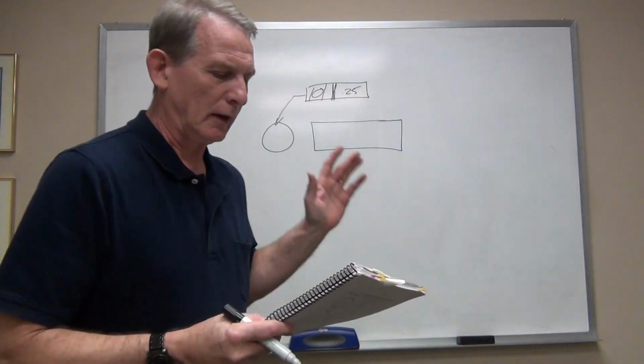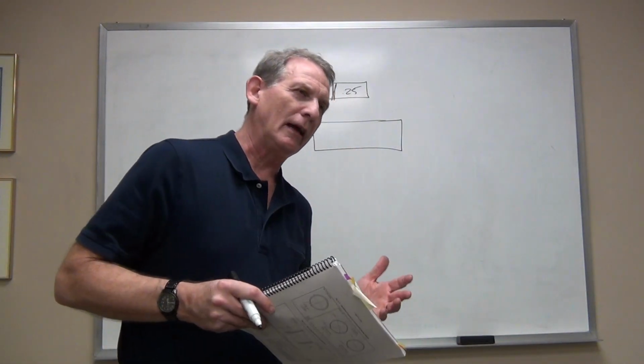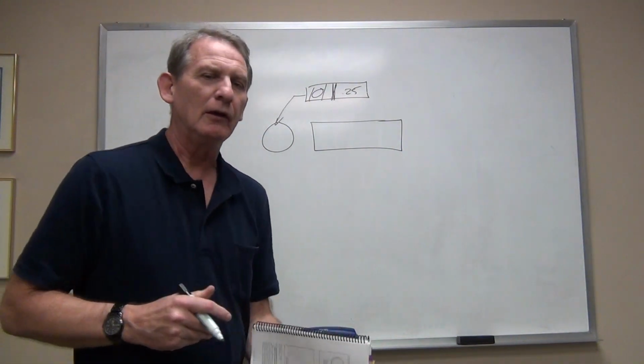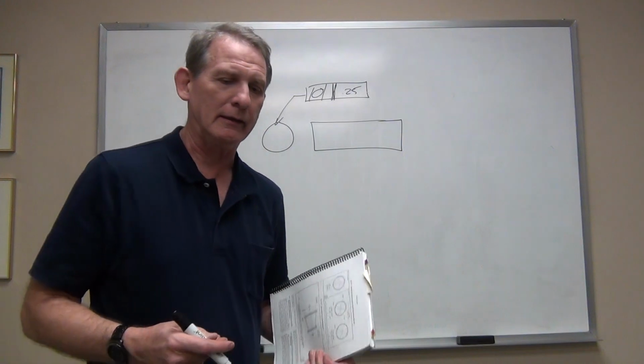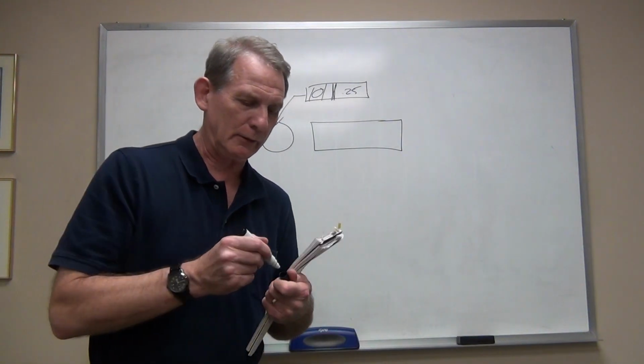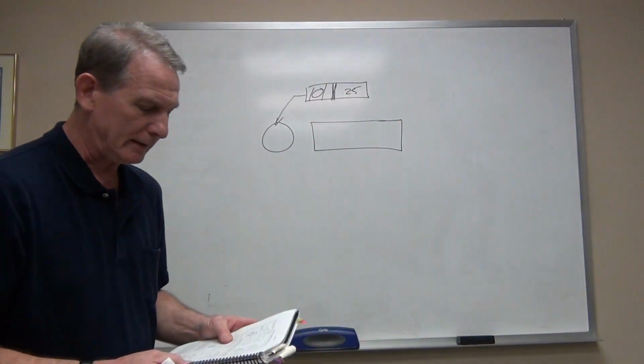Same tolerance zone. We have a circularity call out now here. Again, the thing that you always are going to ask yourself, I hope, is what is the nature of this tolerance zone? It's a different requirement than circularity, so you would certainly expect that it would or could have a different tolerance zone, and you would be right.